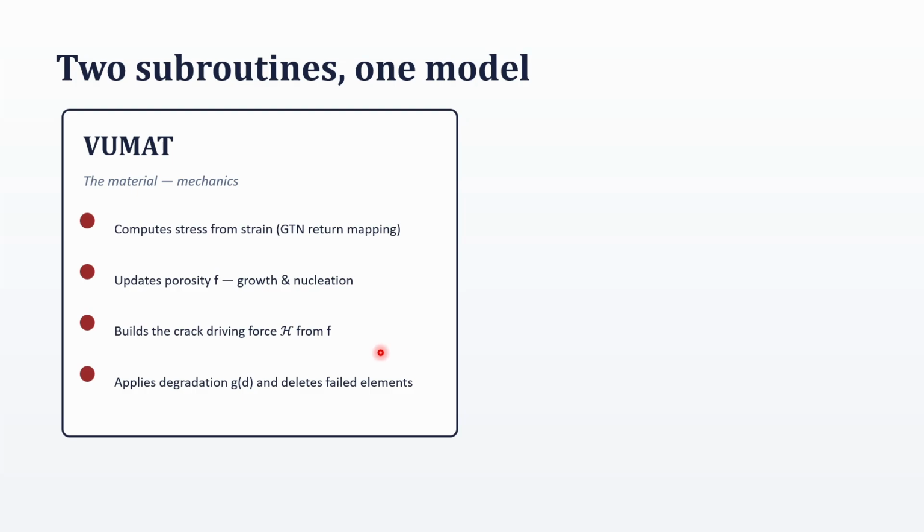So what I use is a stress degradation. When F reaches Ff, I take that element and degrade its stress drastically, so that the effective stress of that element after failure becomes close to 0. But if the stress carrying capacity of an element goes to 0, no matter how small a loading you apply, the element will distort very highly.